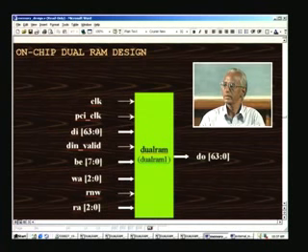Actually this application is also for DCT-Q, which we have seen earlier, and it requires dual RAM. It is not a dual port RAM, mind you, it is a dual RAM, in the sense we have two RAMs inside this black box to start with, and each of these RAMs will be storing the image information, and this information will be written through the PCI bus.